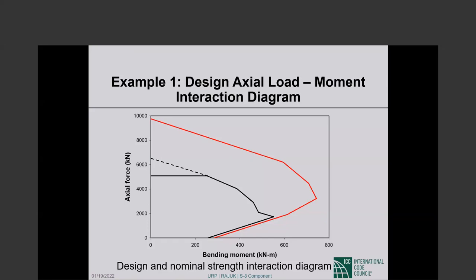If we use a 12-inch by 12-inch column for a certain load and use four 16 mm dia bars, but spacing between longitudinal bars is more than 6 inches, will that be fine? Yeah, that's totally fine.